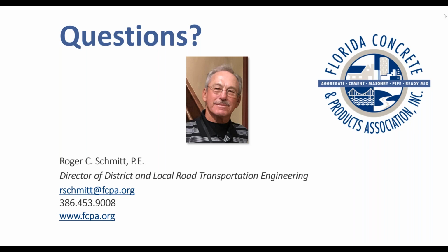What we found before on I-4, where we had concrete and we had the asphalt right next to the concrete without a widened lane, we had a lot of edge cracking. But we also had, which was really strange on I-4, I'm going to call it a tunnel under the shoulder and under the edge of the pavement for quite a distance that had washed out. So I believe in the widened lane.